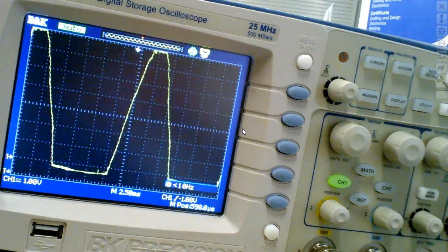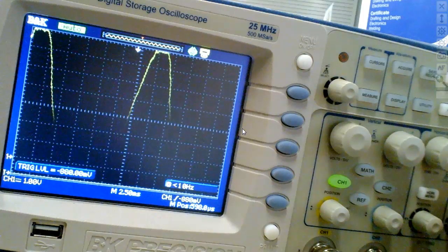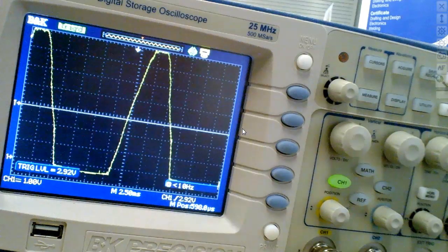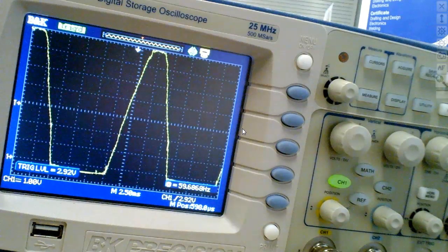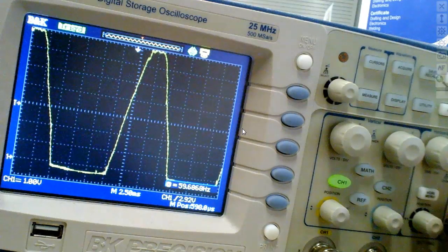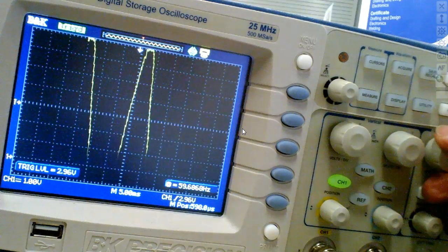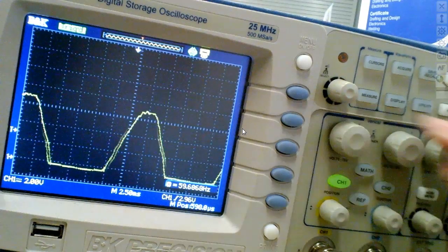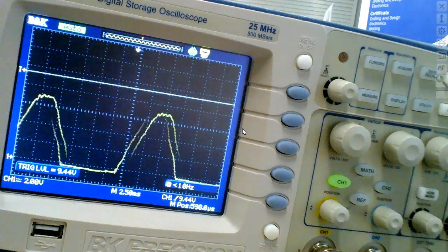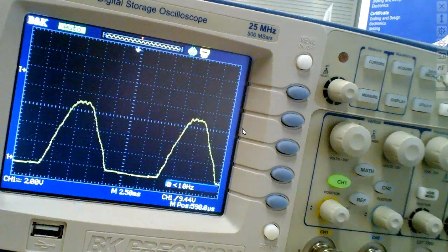So we have a circuit in there that we call a trigger, and you can actually see the trigger, the white line. All you have to do is move that into the waveform. Now the scope is synchronized, and this synchronizes the oscilloscope with the signal it's trying to measure. Does that make sense? If you look at this and it's snaking all over the place, that means the scope is not synchronized with your signal. Right now I'm trying to synchronize it with something way up there, and it's jumping all around, right?